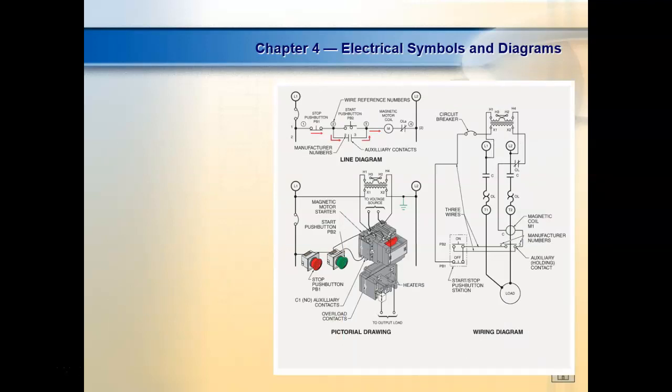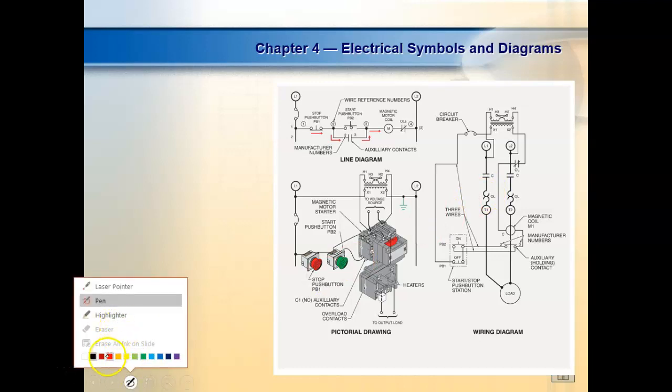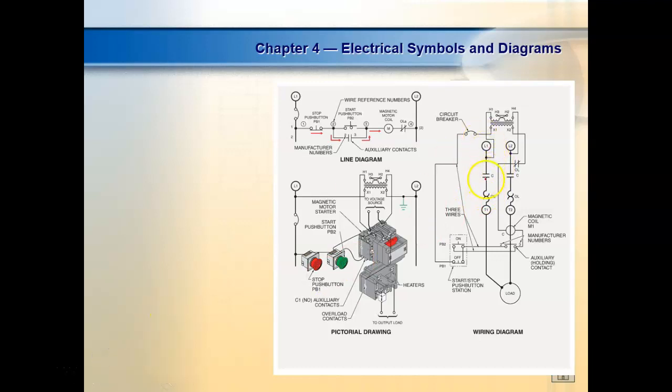So we pick up another symbol. So this right here is the actual sensors that sense the overload. Right here, these hook shaped right here. Now originally we used heaters. So we had a tube, we'll show that, that had solder in it. Solder melts at a pretty low temperature. The heater's wrapped around the coils of the solder. There's a spring in there trying to push. And what would happen is when these heaters got hot enough, it would melt the solder. Now the solder turns into liquid. It's no longer solid. Had a spring on there that would trip out.